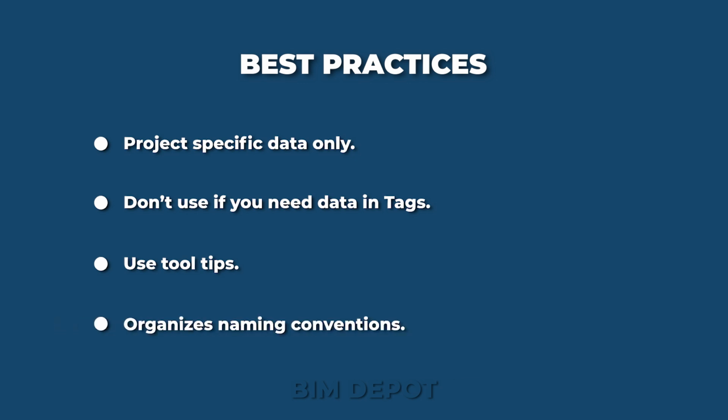And then lastly, keep the naming consistent within the office standards. So you don't want a naming convention that is always jumping from all caps to title case. Then in some instances, you're using prefixes like BD, and then in other cases, you're not. Just establish something that's really clear and understandable for anyone that jumps on the project, whether they've been on the project for months or if they're just jumping on the project for the first time.